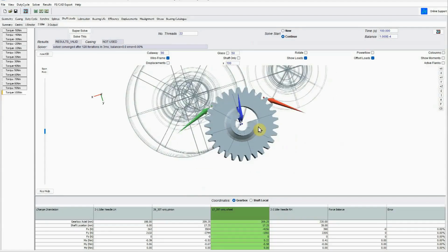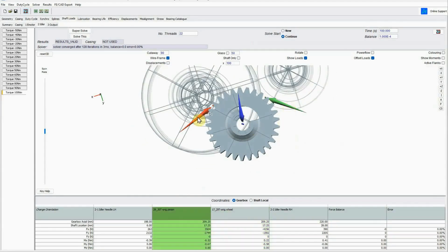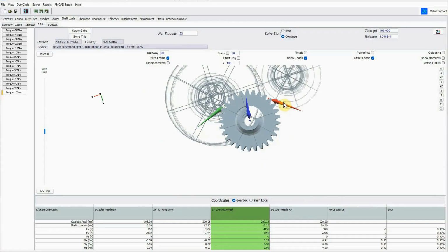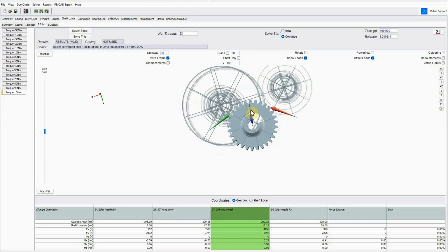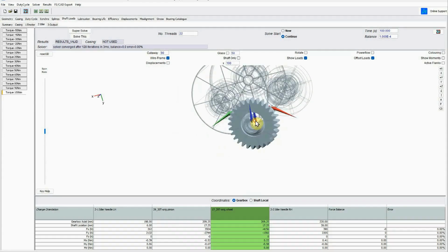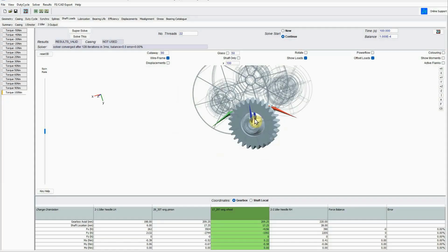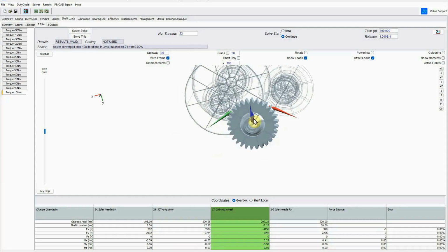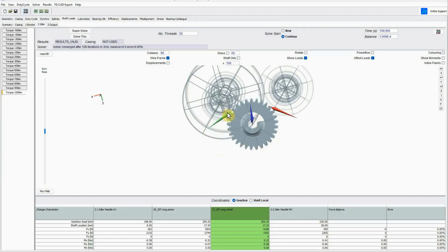shaft by the 2 forces from the gear teeth, and you can see here that to quite a large extent these 2 gear forces are now cancelling each other out. So that means that the reaction forces that the bearings are having to react are much lower, and that is why we have an improvement in our damage to less than our damage limit. The next thing we can do is generate some efficiency maps, which is what we'll show next.